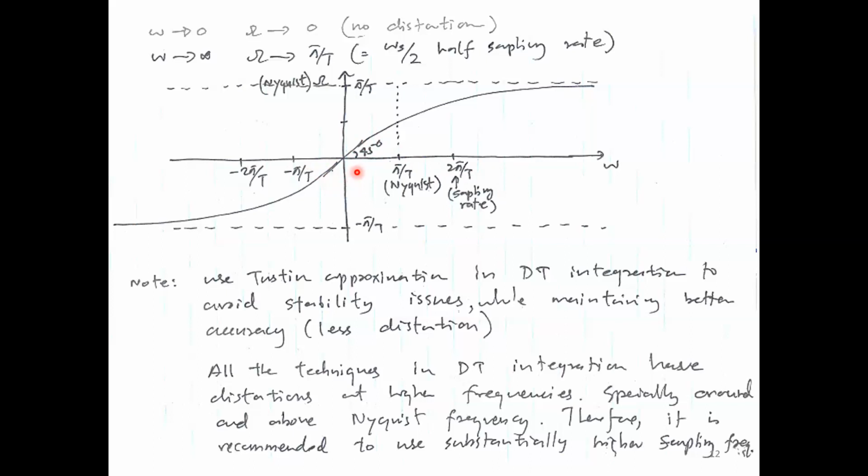So then you can say this, I want to have a very accurate numerical integrator. I will use Tustin for that. And also I want to have the system to have stability. Again, Tustin is good. And I also don't want to see frequency warping, right? When it comes to that third point, I would say I will stick to the frequencies in this area, right? Around the origin. So therefore, the graph between omega and capital omega is a linear portion.